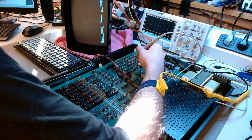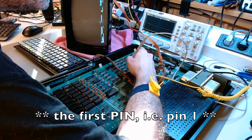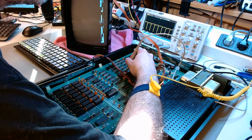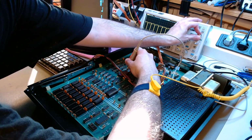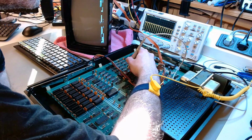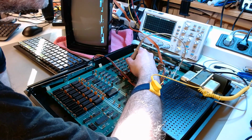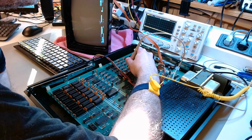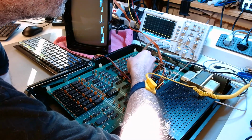So let's look at this shift register. The first bit is the shift load bit, so it triggers a parallel load when it's low. And you see every few cycles it triggers a parallel load. That's exactly what we would expect. The next one is the clock, and there are 2 clock inputs. One of them should trigger a shift. This one seems to be floating. Very interesting. We have a floating clock input.